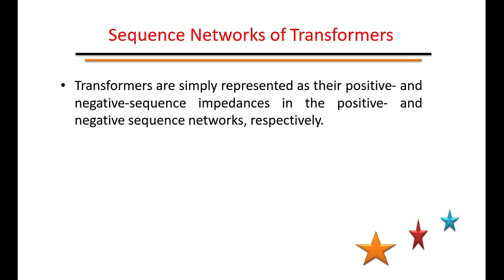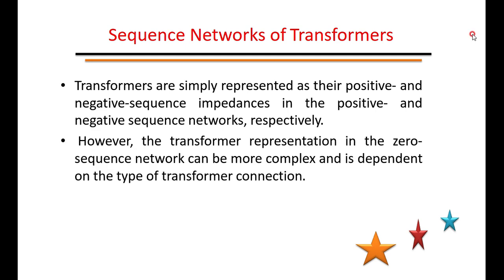In the case of the transformer, it is a static and passive device, and in the positive and negative sequence it is represented only by its reactance. However, the representation in the zero sequence network can be more complex in the case of the transformer, because it depends upon the type of transformer connection.